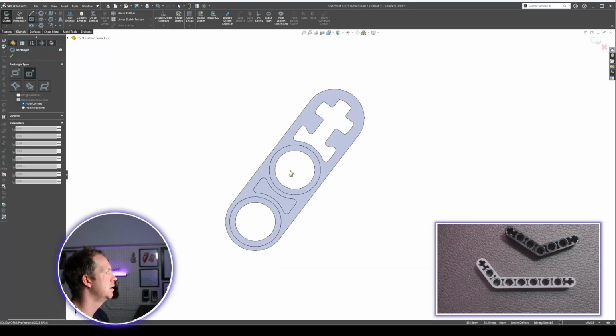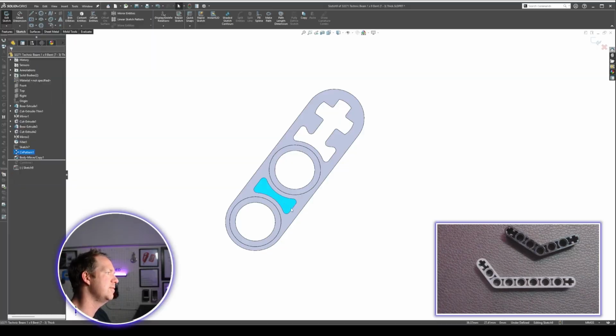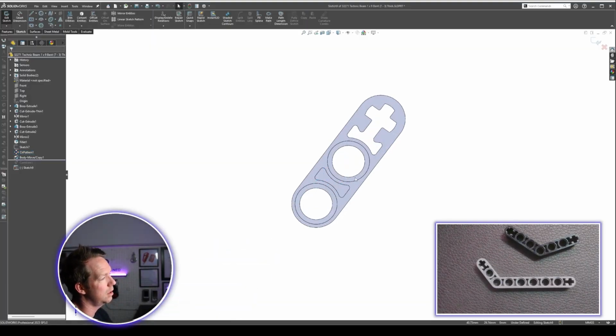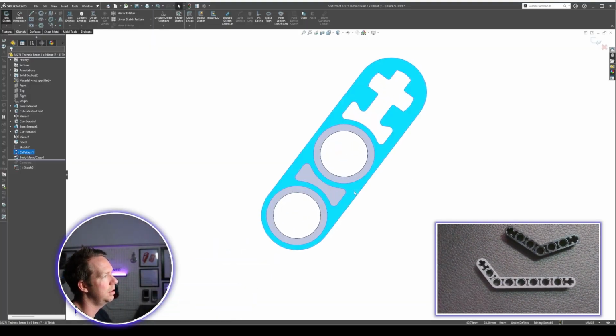Now the sketch, I'm going to make it concentric to the hole. And where I'm going to split it is on the edge that is closest to the open space. What I can see here is if I want that section to be repeated, so one hole and one hourglass recess, that's what I need to sketch here to split this body in 3 parts, and then use that split section to replicate. So it's a little bit complex, but if you've got the right eye and understanding of your geometry, it becomes a relatively simple task.